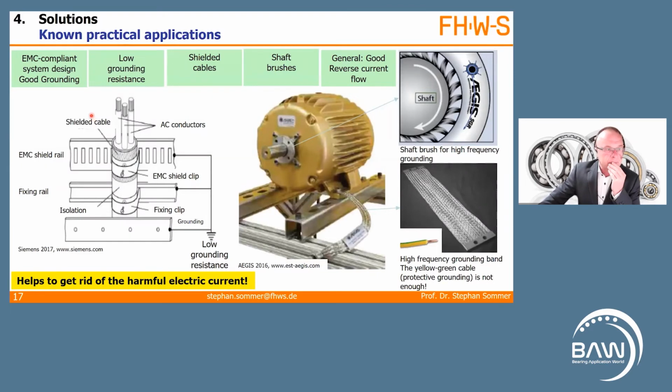Well, here are EMC compliant design, a good grounding. And Siemens shows us how this works. Here are the AC conductors for the 3 motor phases. And here is the shielded cable. The shield from the cable is connected to an EMC shield clip. And this EMC shield clip is connected to an EMC shield rail. And this is ground